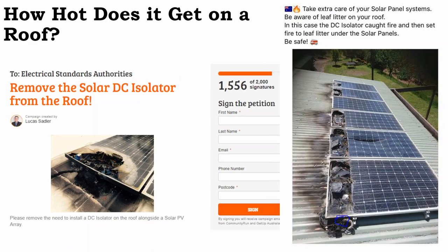Another aspect is debris can accumulate underneath the solar array. And if you get debris accumulating around that box, that can be a fire hazard as well. To the point where it's not a bad idea to budget a little more money and put a metal netting around the perimeter of the array. Most installers don't do that. I'd say it's not a standard practice, although I know solar companies who have it be a standard practice.